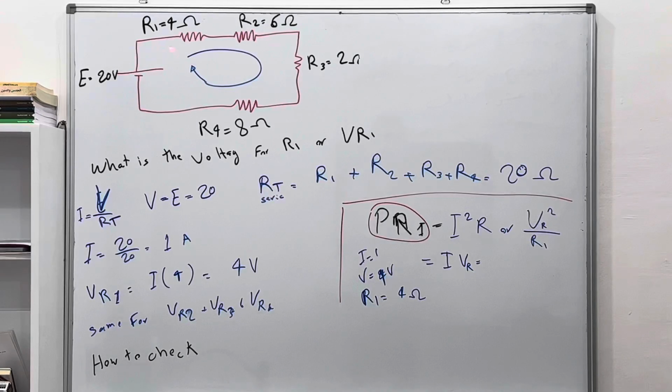As you can see now, R1 and R2 have one common point, which is here on this red line. They don't have any other common points. So that's why R1 and R2 are series, not parallel. And again, you see R1 and R3 have one common point, not two. The second point here is shared with another resistance, while the first point for R2 is shared with R1.